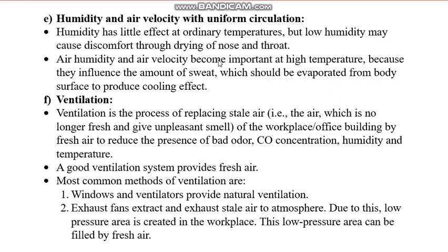Air humidity and air velocity become important at high temperatures because they influence the amount of sweat, and the sweat should evaporate from the body surface and produce a cooling effect. But if the sweat is not evaporating, you won't feel cool. You will feel some kind of discomfort, and you will not be comfortable in such situations. That's why you have to maintain the humidity.